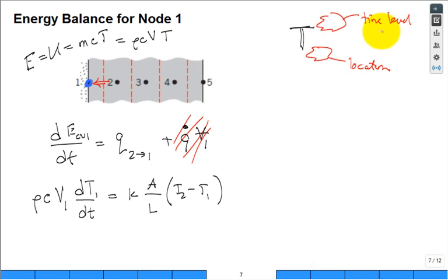Because we're going to have time stepping, right? So if somebody said, this is the temperature of node 2 at 5, well, it would be the 5th time step. Starting where the temperature of node 2 is 0, that would be like initial. And then temperature node 2 after 1 time step, then after 2 time steps, 3 time steps, etc. So you'll see this temperature at location I level P. And then you'll see temperature at location I level P plus 1, the next time step, the next time level. This is used in a lot of textbooks.